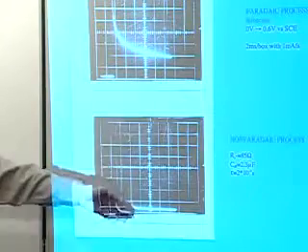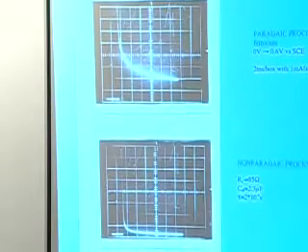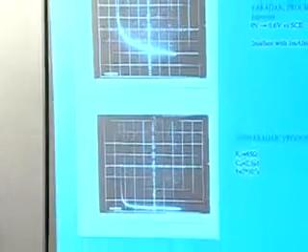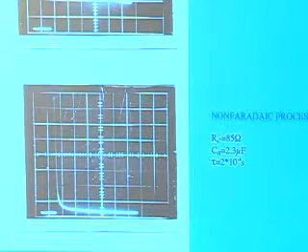What probably you can't tell for certain by eye is that there is an exponential decrease in the current right there. In fact, you can take that curve and back out that I have 85 ohms of resistance there and a capacitance of about 2.3 microfarads. If you need a ballpark number for just about any metal electrode, it's about 20 microfarads per square centimeter of electrode. It's about a tenth of a square centimeter that I have there, so it works right. Great rule of thumb, if you just need a guess at the RC time constant: 20 microfarads per square centimeter. And in this particular cell, I get an RC time constant of 0.2 milliseconds when I carry out that experiment.